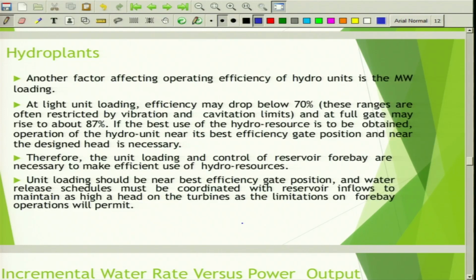The power transformer usually operates at rated load, right. So the peak efficiency is designed in such a way that the constant losses and the variable losses are equal at the rated load condition, right. Whereas the distribution transformer is not loaded at its rated capacity all the time. That is why we carry out all day efficiency, right. So this distribution transformer is designed to operate at its maximum efficiency at less than its rated load, right.